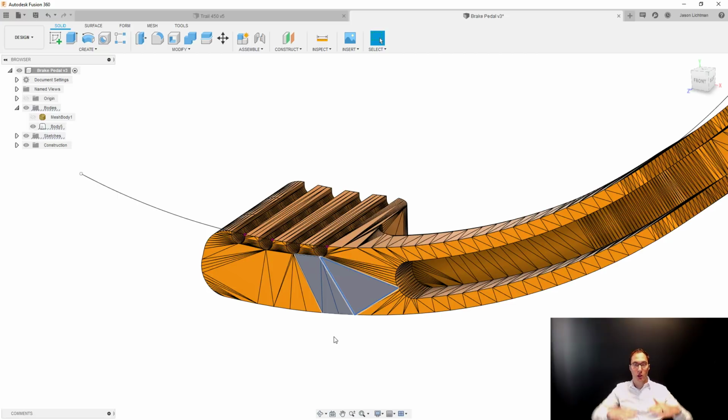If you look at the angle between them, it should be 0 degrees or something really, really infinitely close to 0 degrees. And our software does have tolerances in there as well. So what I could do is select one of these triangles, and when I hit delete, it's going to try to take the other triangles that are nearby and extend them so that it fills in that empty area. But if it sees that a bunch of those triangles are within tolerance of each other and pretty flat, it'll actually merge them all together.